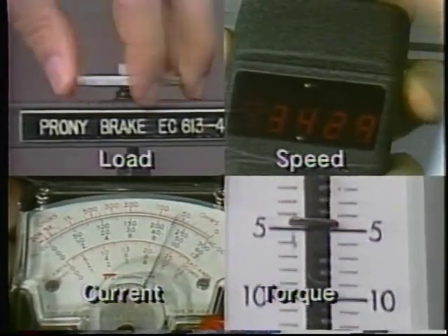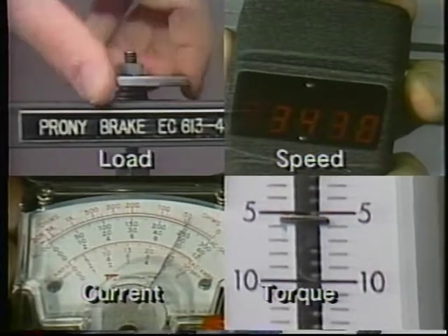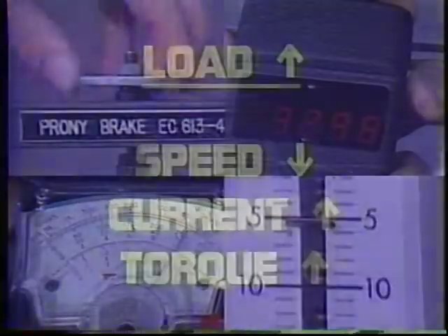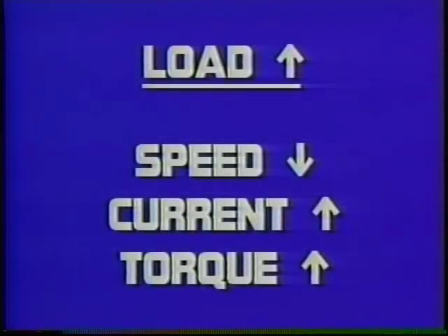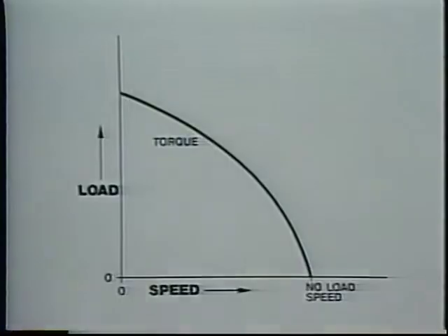This basic relationship between load, speed, current, and torque is important to keep in mind, particularly when troubleshooting motors. We will see it applied frequently in later lessons. Here is a graph of what we have been looking at so far. It's called a speed-torque curve.